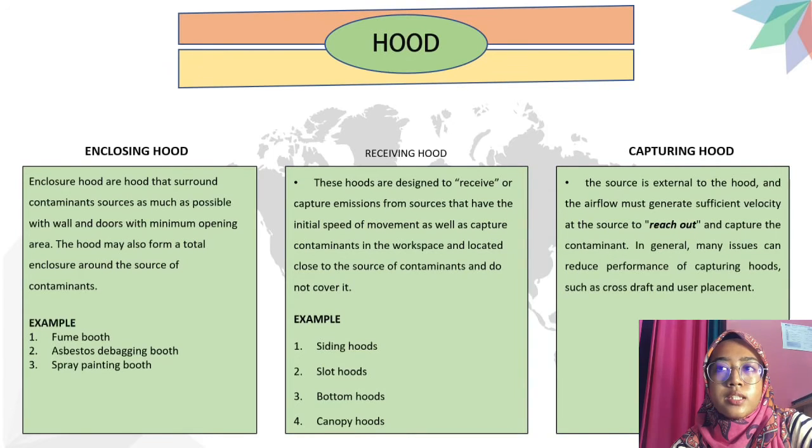The third category is capturing hood. In a capturing hood, the source is external to the hood and the airflow must generate sufficient velocity to reach out and capture the contaminant. In general, many issues can reduce the performance of capturing hoods, such as cross-draft and poor placement.